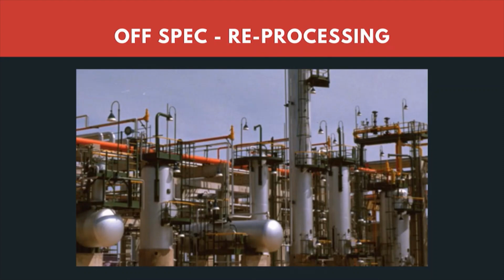The off-spec LPG will be routed back to the amine treating unit or Merox treating unit, and the H2S will be knocked off. But again this is going to take time and effort. When you are doing reprocessing, the particular plant throughput may have to be reduced, and a lot of effort is involved.